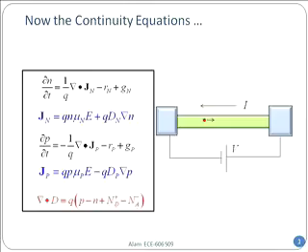Now, as I have mentioned several times before, there are these 5 equations. In fact, 3 equations, if you count properly. The first equation is the continuity equation for electrons, and I'll explain what I mean by continuity. Then there is an expression for the current, and the second equation simply says how the current responds to electric field and density gradient.